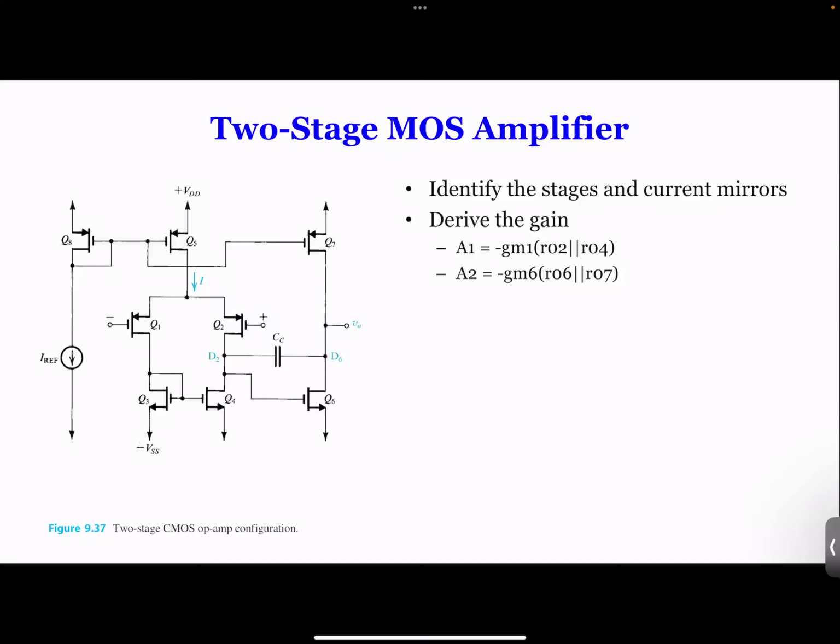There are two important things. One is the DC biasing. The DC biasing is the circuit has to work in, like MOSFETs, they have to work in a saturation region. And for BJTs, they have to be in active region. So the DC biasing is important to make them work in those regions. If something happens, the biasing is changing, and then these MOSFETs will start to leave their saturation region. Therefore, you can no longer use the amplifier. Either into the triode mode or cutoff mode. Either way, your amplifier is no longer valid. So that's why you have an input range.